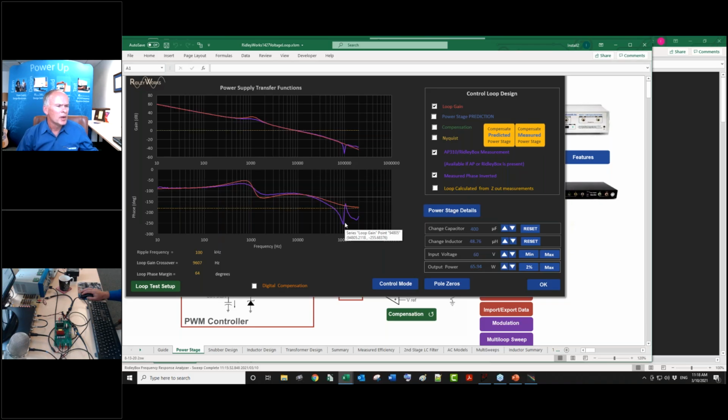Somebody asked about me twisting the wires going to the output. Quite honestly, that's just for neatness. We're injecting fairly low frequencies here, and then we're shorting the injection wire with a 20 ohm resistor. So if we were to pick up RF, the 20 ohm resistor would take care of that. But yeah, I just try to be neat with cables. You don't create loops and mess.